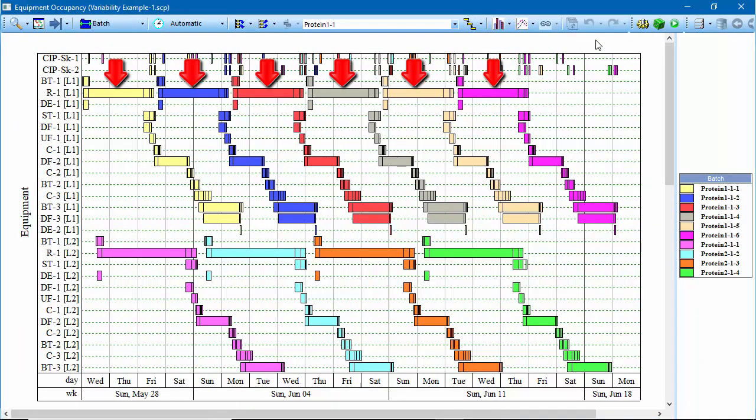Here you can see the consistent durations for the ferment operations in both recipes. Note that each campaign in this example was given some slack time between consecutive batches in order to accommodate small delays which may occur during a given batch. Next, the impact of operation variability can be studied by clicking the Play Simulation button. When this button is clicked, a single potential outcome of the schedule will be simulated by selecting variable durations for operations which have been assigned probability distributions.